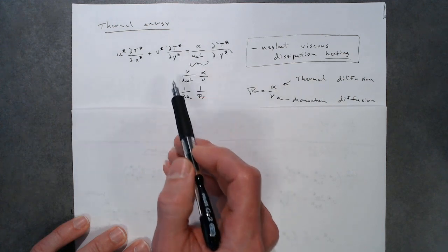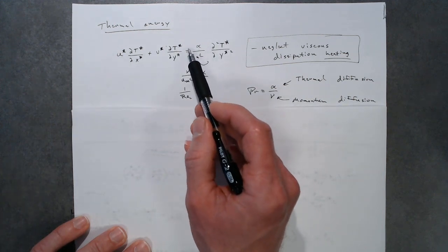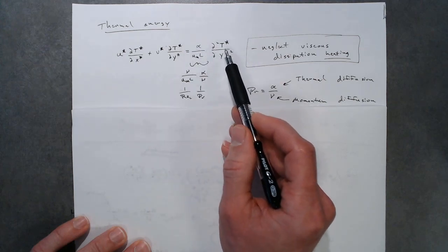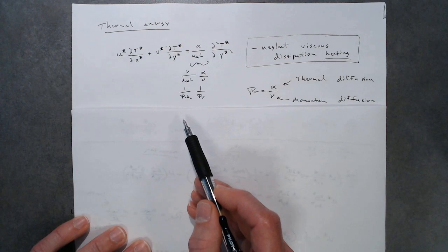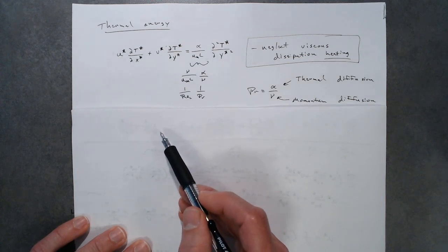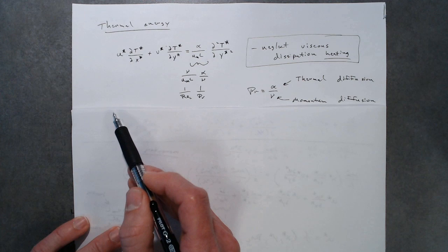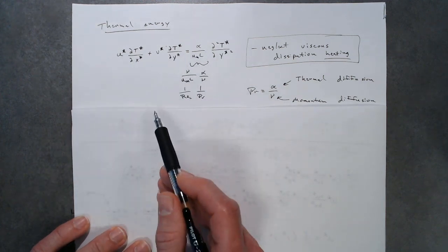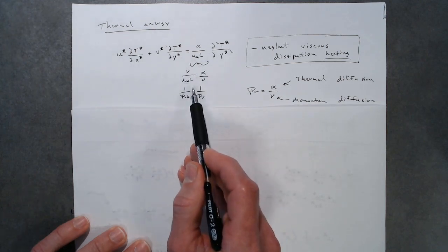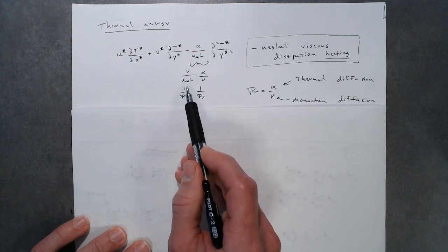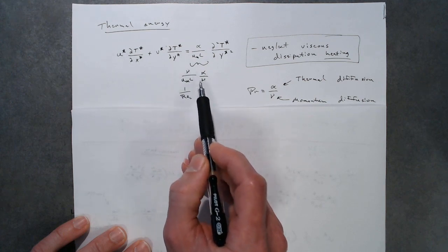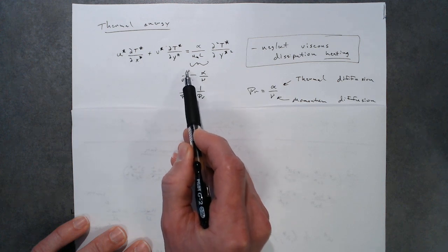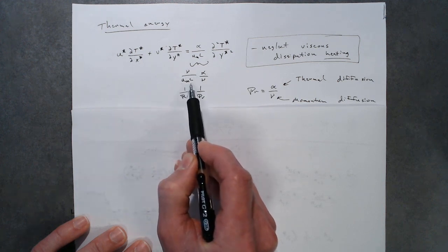So when we make this non-dimensionalization, if we work through the arithmetic, then we see that the prefactor for this diffusive term becomes alpha, the thermal diffusivity, which is k over rho times C sub p, divided by U times L. Well, we can expand this into two terms by multiplying by nu over nu, and have one term that's kinematic viscosity, nu over velocity times length scale.